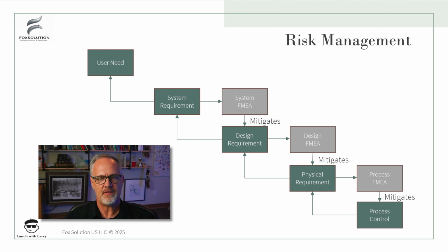So these FMEAs become part of the data model and explain, from an occurrence standpoint, how often some problem can occur to lead to a problem where the next level up isn't delivered. And the nice thing about this is each one of those lines has an occurrence associated with it. So we can say what we believe the occurrence of some problem is going to be.